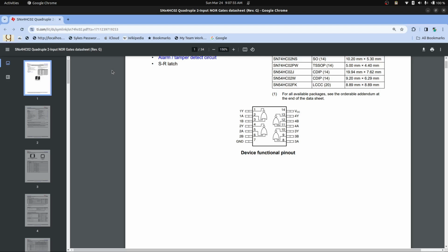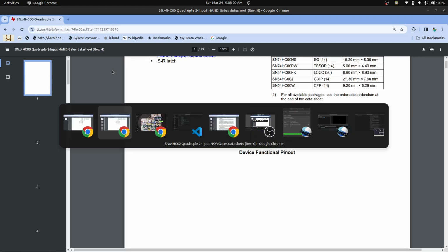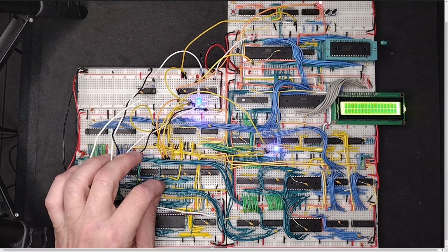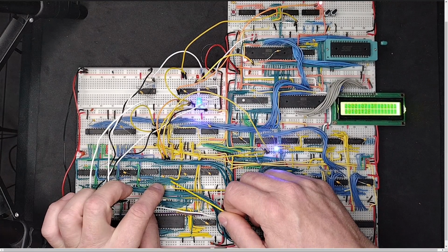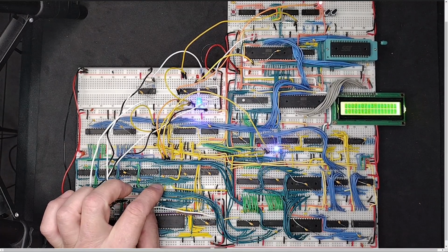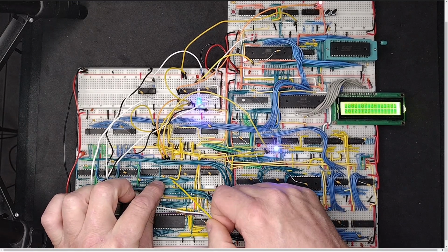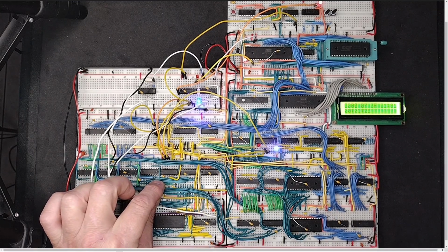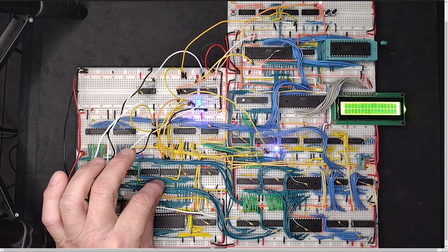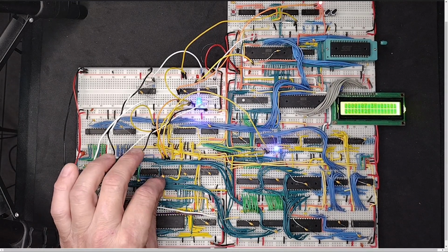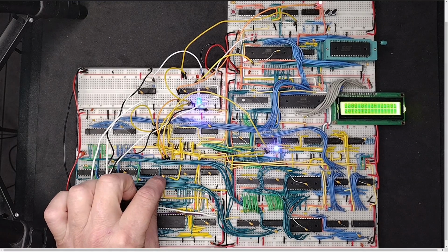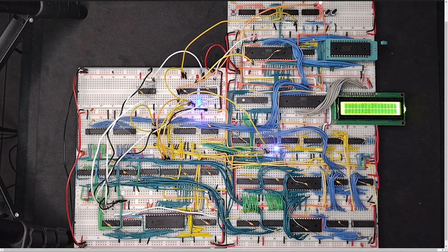The effect of that is that if you wire your latch exactly the way that you would wire it for a NAND gate, then the actual location of the Q and Q prime outputs are the same as they would be for the NAND gate. So I don't know if that's why the NOR gate is wired the opposite of every other chip, but I think it might be because it is very common to use NOR gates and NAND gates as SR flip-flops.